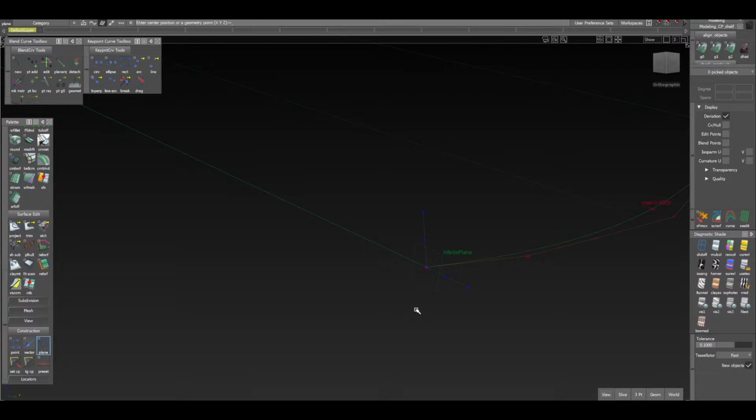So what we're going to do is hit Control Shift, left mouse button, pick object, because it's an object. It's not a curve, it's not a surface, it's not a line, it's not a span, it's an object. We're just going to click it just like that. Okay. And then we're going to move our cursor over under the construction tab, and we're going to hit set construction plane, like so. And you'll notice that the view cube has changed. Okay, it looks all weird now.